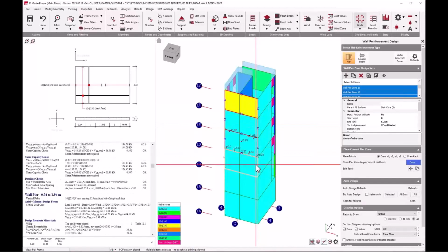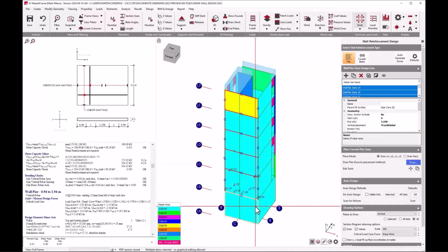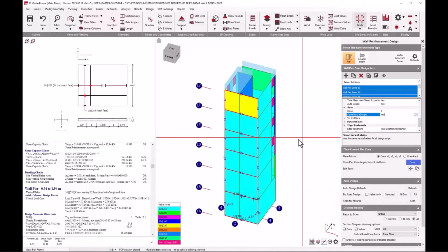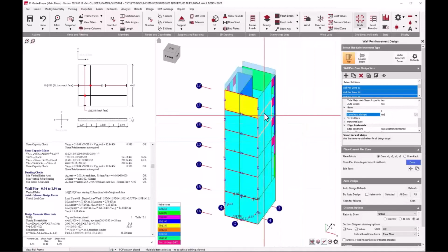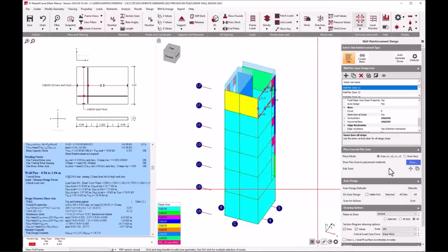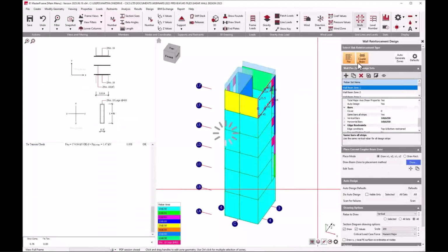A really useful trick is to be able to multi-select them, more than one item. We could window all of those quite easily as well. In the multi-select, you can make some really quick rationalizations. Selecting multiple items, you can quickly go and say, well, I would like all of these potentially to be the same reinforcement, so that you can quickly rationalize all your various different design regions to have some commonality. Small little 1% overstressing there.